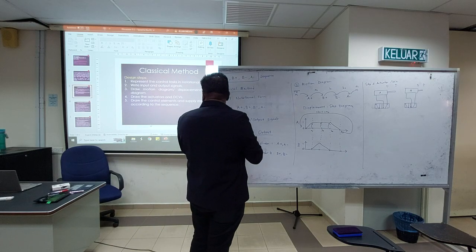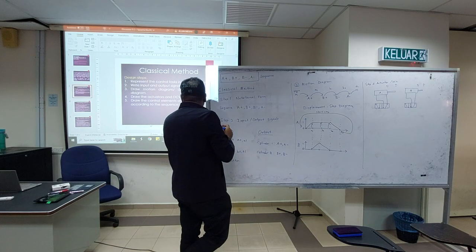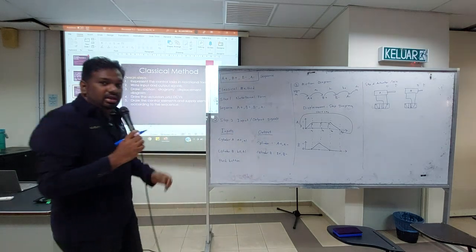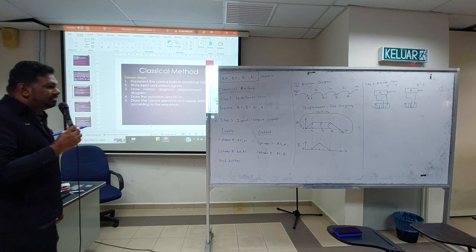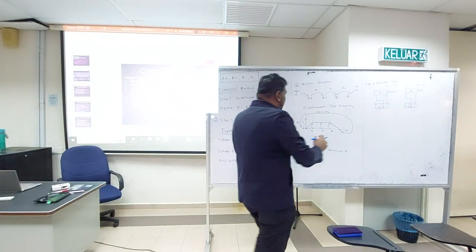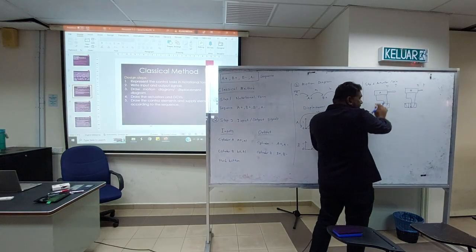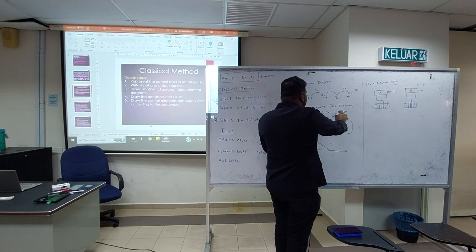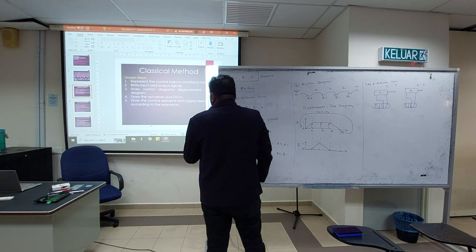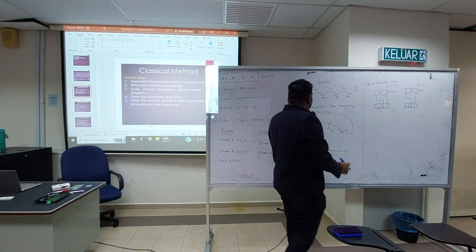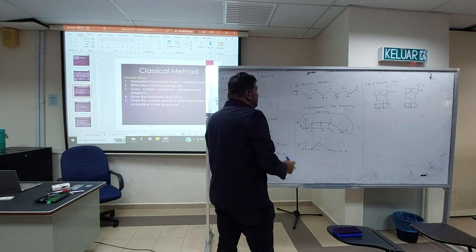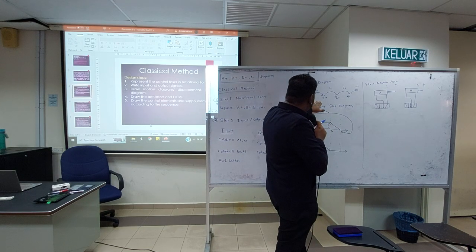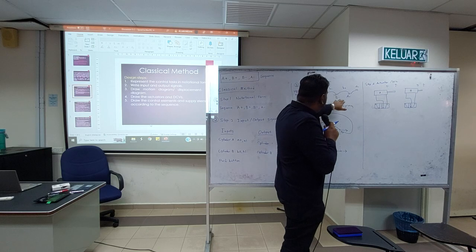So draw the actuators and directional control valve. Then step number 5: draw the control elements and supply elements. Once you have drawn this, we will start with the power element. Then according to the sequence, you put all the control elements and also the supply elements. For here, follow the sequence A plus, B minus, A minus.